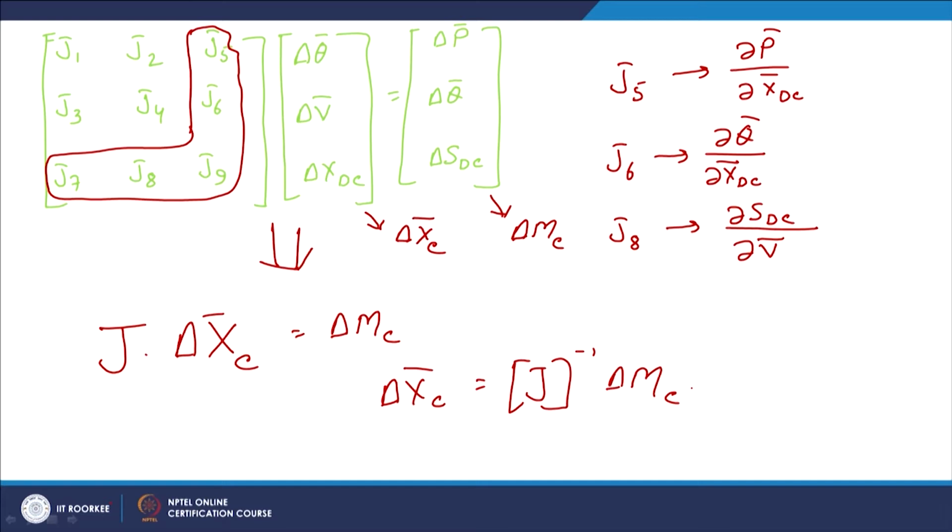In the simultaneous approach, we simply take the equations as well as the unknowns of the AC and DC system together, and then solve by the standard Newton-Raphson method. This is straightforward, but the problem is that the Jacobian matrix size increases depending upon the number of unknown quantities.